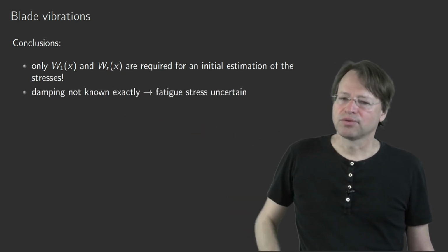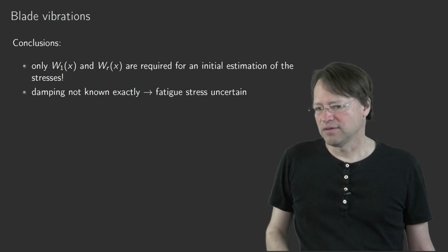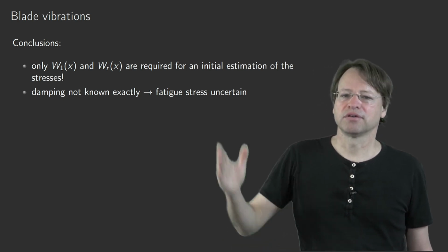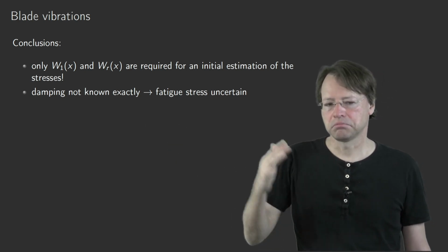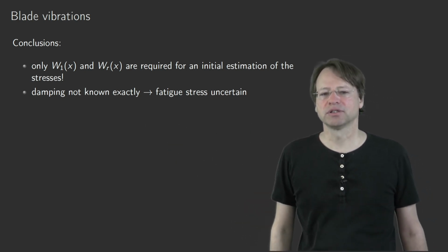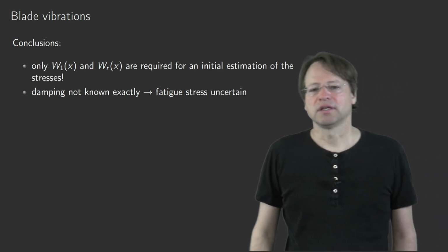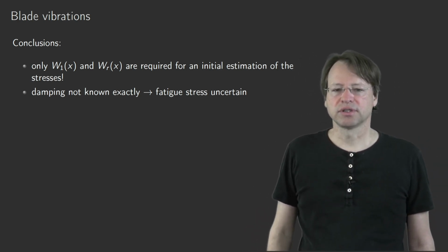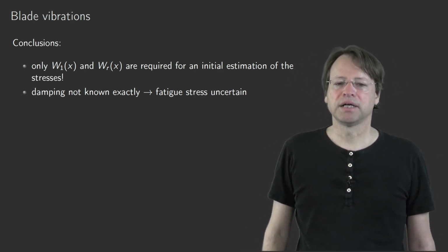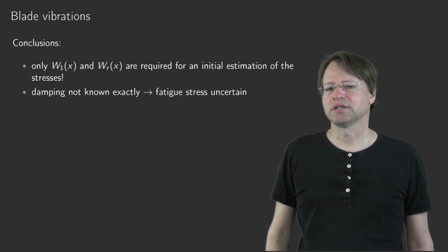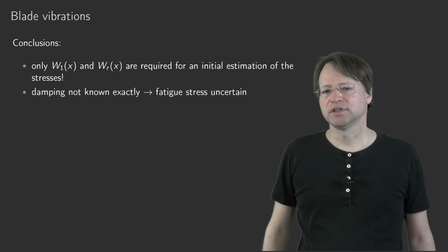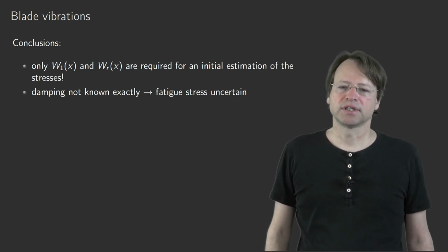For the damping, of course, damping is never very well known. So the fatigue stress is uncertain with respect to damping. You take, I would say, a safe approximation of the damping into account in your system. But the damping, also in measurements, changes very heavily and affects the result, and this leads to a certain uncertainty.